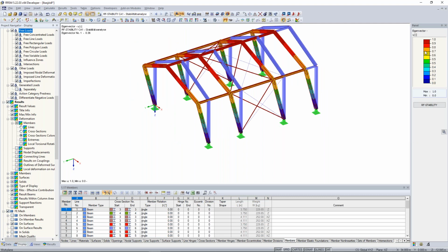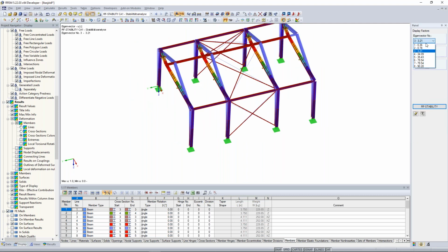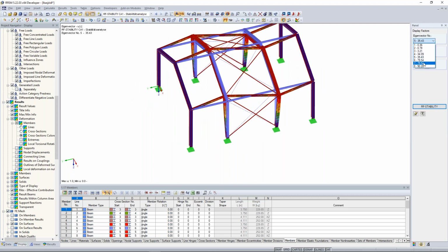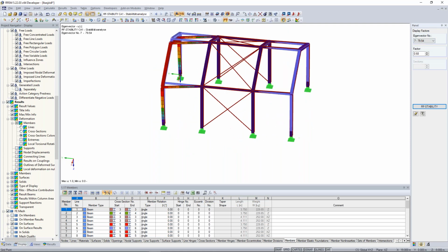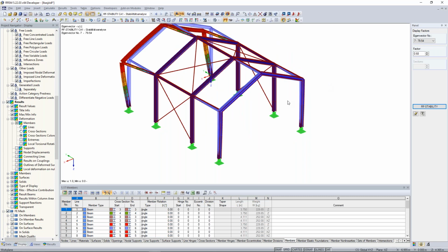And we can look also at some local problems, but I think there are just some global problems. But it can be possible that one column is maybe too weak, and this would mean that we have there a local problem. And the first reaction when one column is too weak is that we increase the size of the cross section of that. This would maybe be one solution. So this would be helpful, to look at more than 1 or 2 eigenvectors. Okay, good. Next question.